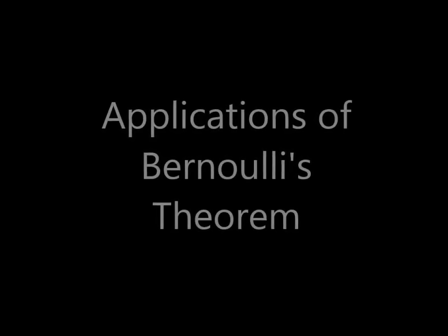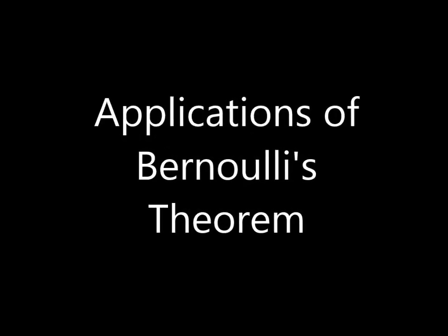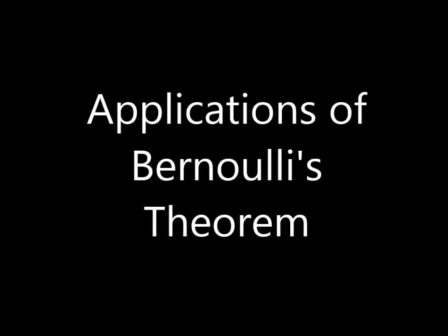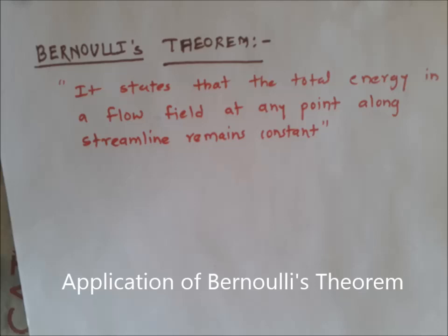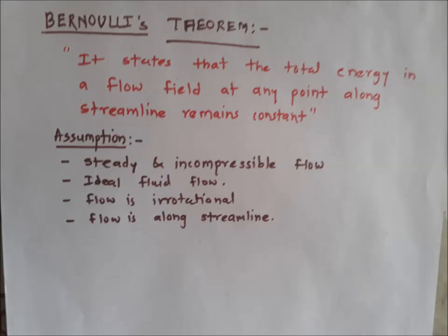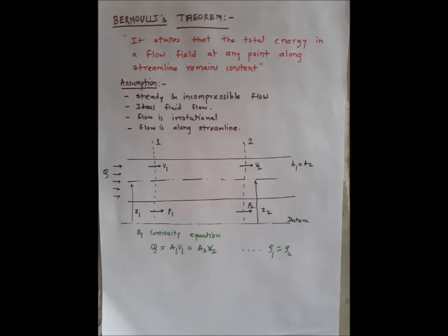Theorem. First of all, we will see Bernoulli's theorem. It states that the total energy in a flow field at any point along the streamline remains constant. It is nothing but an energy balance equation. The assumptions made in Bernoulli's theorem are steady and incompressible flow, ideal fluid flow, irrotational flow, and flow along a streamline, where ideal fluid flow means the flow is